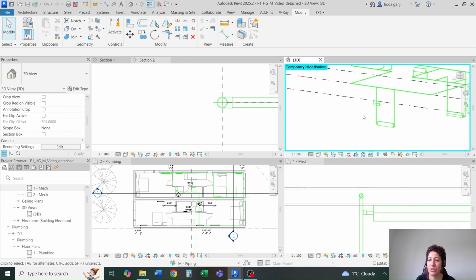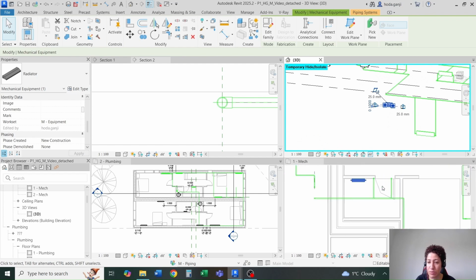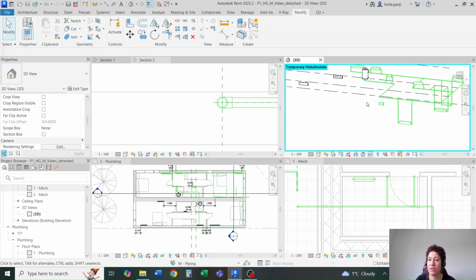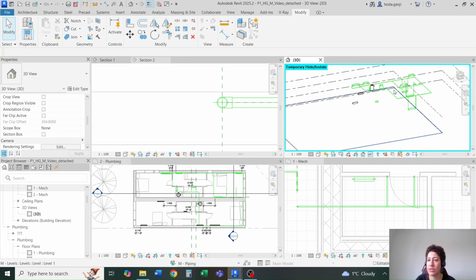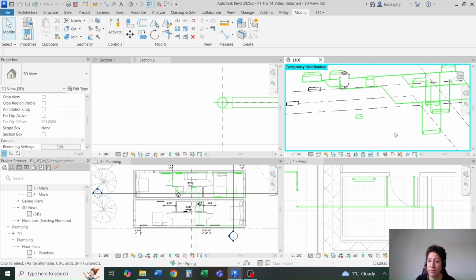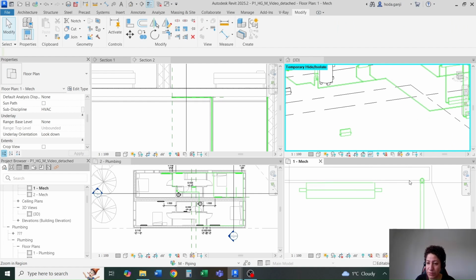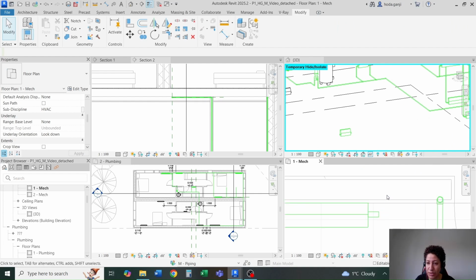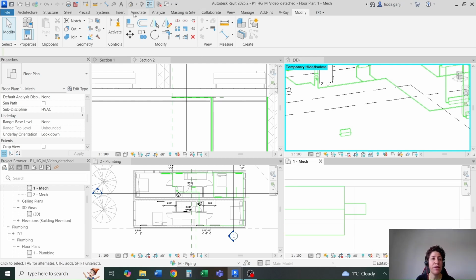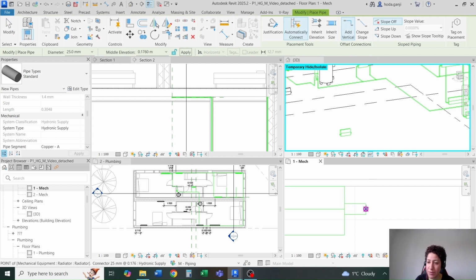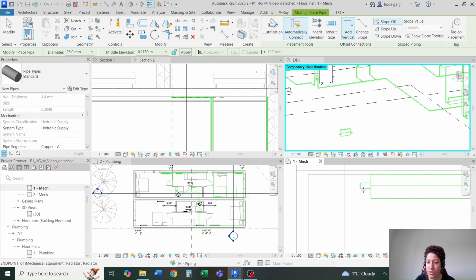So this looks good. There is one more radiator on level 1, which is in the bathroom area, and that's the last radiator that we need to connect, and that would be all radiators for unit A. So for that one, maybe we can get a branch from this part. How about first I create a connection that goes into the wall. So I'm going to go with level 1 system. I'll go with the pipe, one pipe here going into the wall. And on the other side as well.